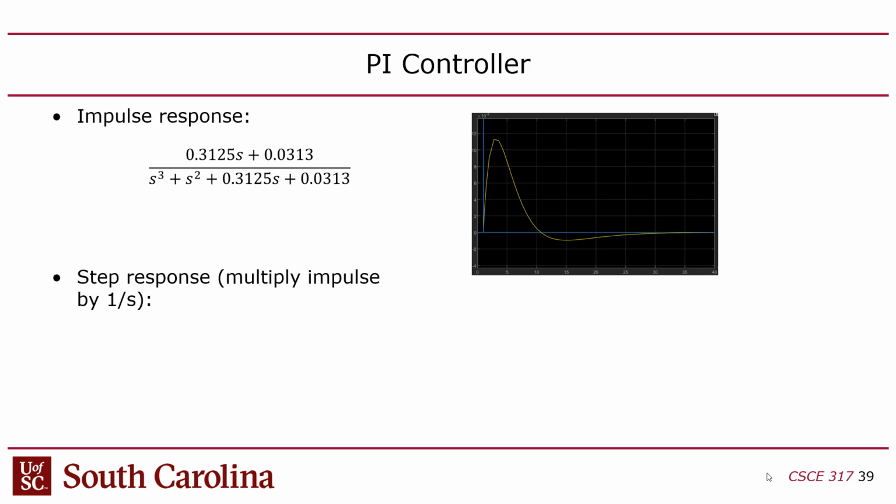Why is it not great? Remember, the impulse is a stand-in for the set point, right? So what I'm really doing is like driving my cruise control, and I set my cruise control setting as an impulse. And then I want to see the corresponding process variable, which is the speed of the car. So this yellow line is supposed to track the blue line as closely as possible, and it's not really doing that very well. I mean, it doesn't go to infinity, but it kind of goes up.